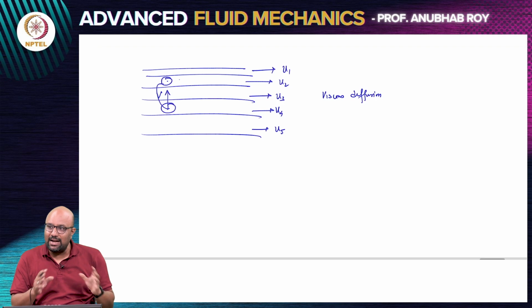So finally the entire picture is all about momentum transport. There is momentum transport due to viscous diffusion, there is momentum transport due to advection. And this is a problem where both are actually competing. And what we saw is that in this competition, even if you say that there is a parameter multiplying viscous diffusion which is very small, it doesn't mean that advection is always winning everywhere.